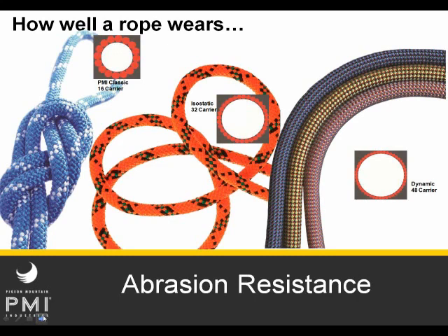The flip side of this is that the rope with greater abrasion resistance, the rope with a fewer number of carriers, is also going to have the lower knotability. It's going to be stiffer. Everything is a balance, and gaining one thing usually means compromising something else.